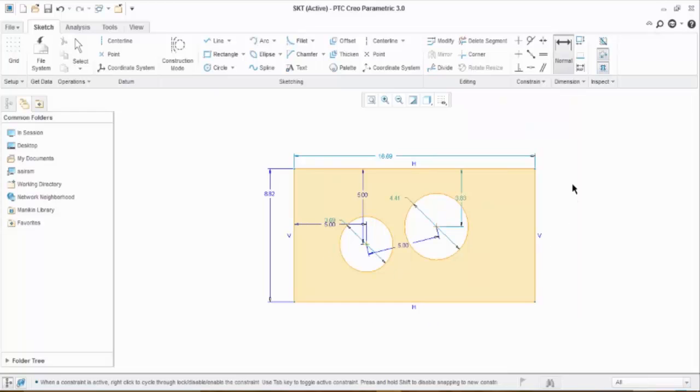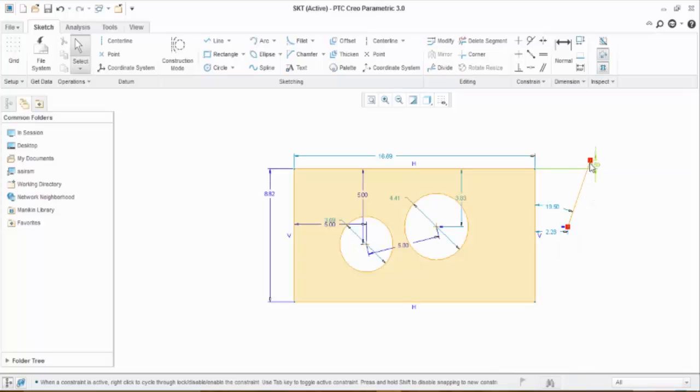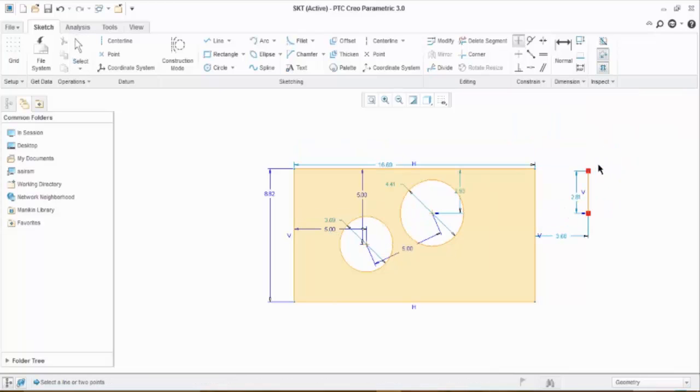Any doubts here? If we want an additional dimension, we can provide it from here, which is create dimension that references sketched or reference entities. And the second option is called constraints, geometrical constraints, right? This is a line command, but this is not horizontal, this is not vertical. So here specify the vertical constraint. Click the item, then it will become vertical.